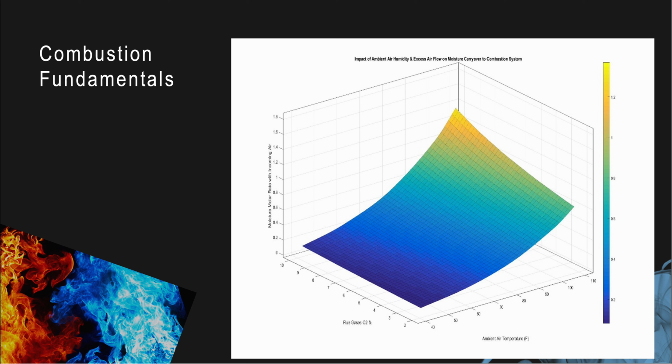So when I take that metric and translate it into something else, here is my air temperature again, and look at how the flue gases oxygen would look. Basically, I have excess air. This is the lump sum air to gas ratio.